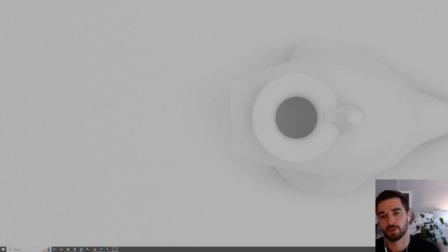In this video, we're going to cover some similar content as previous Grasshopper videos, but this one is going to include some Boolean operations, which in Grasshopper are called solid operations. So we're going to structure this pretty similarly as previously, where we build a point in space, build a curve from there, and then construct a volumetric geometry around that, and then perform these Boolean operations to give you another idea on how you might use Grasshopper to variably control design outcomes.